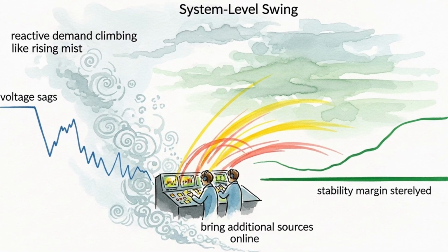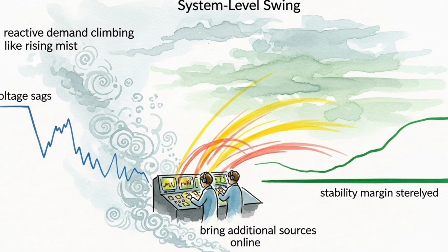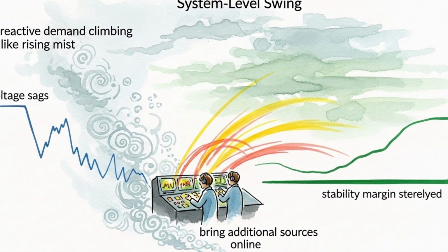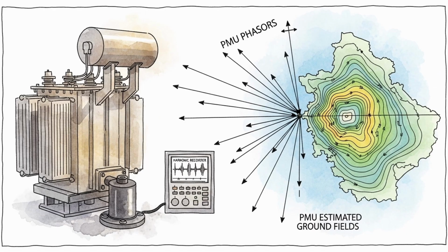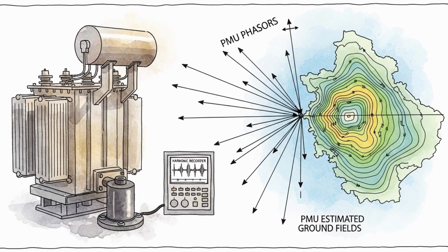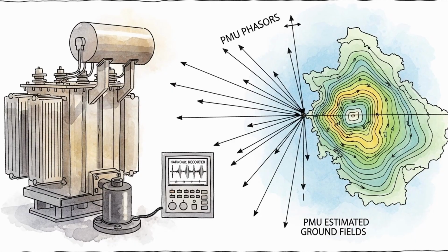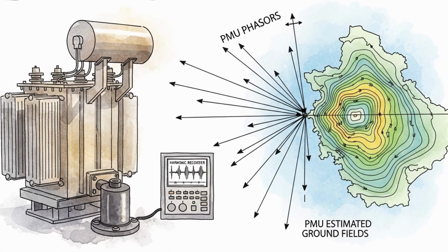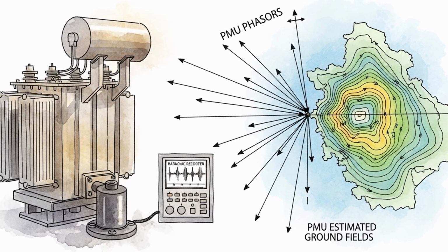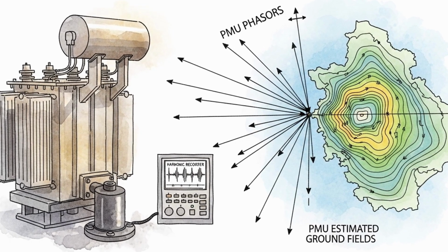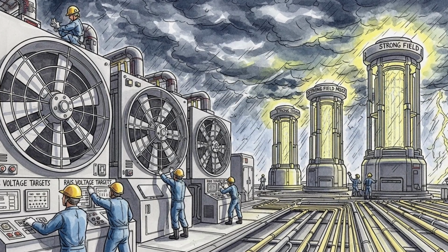The length and path of conductors control exposure. Long, nearly straight lines collect more induced voltage end to end. Power grid transmission lines that span hundreds of kilometers are sensitive. Pipelines and railway signaling conductors also respond. Orientation matters. Lines aligned with the direction of the induced electric field see larger end-to-end voltages than lines at right angles to it. Network grounding practices and transformer connections further shape the current paths into substations.